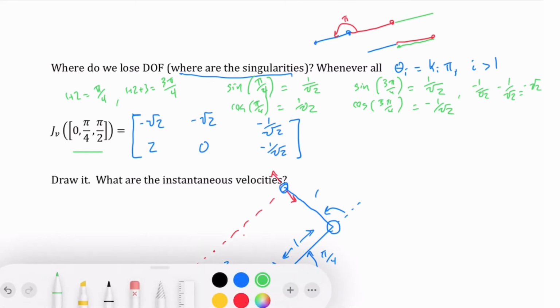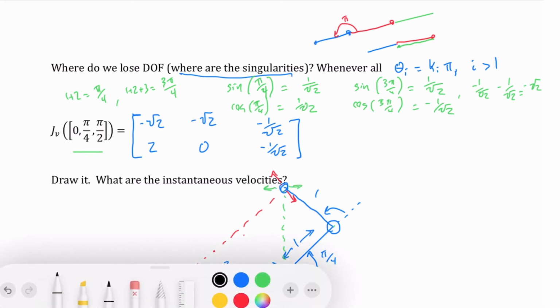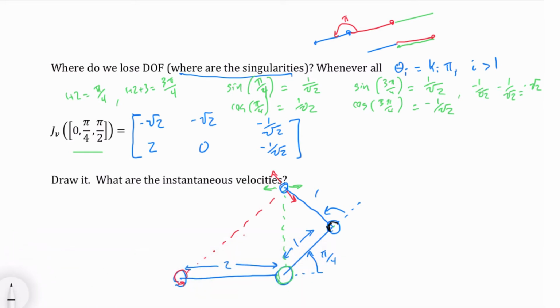If I take my next degree of freedom and rotate it around here, that's going to instantaneously rotate it in this direction. And then my third degree of freedom, by rotating around here, I can make it instantaneously move back and forth in this direction. And since those don't all overlap, I do have control in 2 degrees of freedom there.